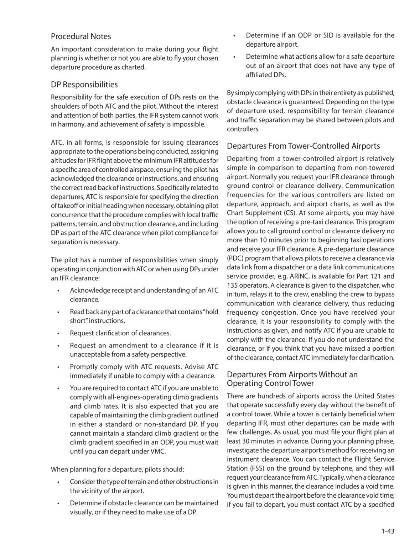At some airports, you may have the option of receiving a pre-taxi clearance. This program allows you to call ground control or clearance delivery no more than 10 minutes prior to beginning taxi operations and receive your IFR clearance. A pre-departure clearance (PDC) program allows pilots to receive a clearance via data link from a dispatcher or a data link communication service provider, for example.